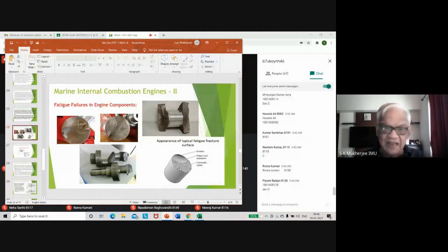Well, sometimes it can happen if the hole does not have a correct fillet radii. That means it has a sharp change of section. So that is why the holes at the entry are made smooth, so that there is minimizing of stress concentration.